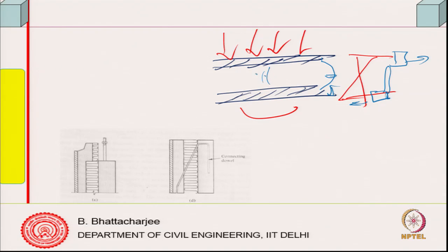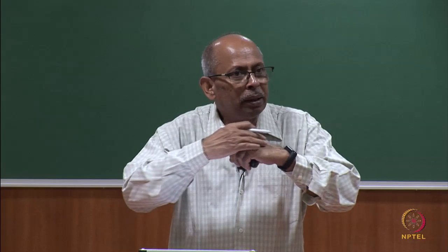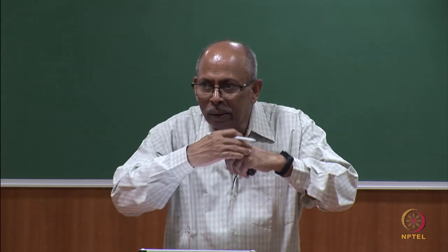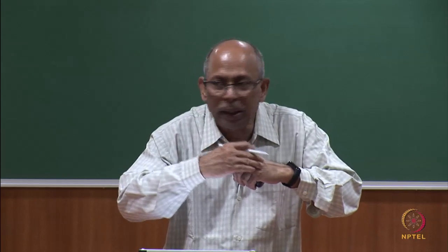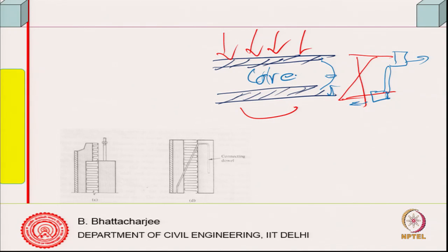So, this in between core, through developing shear stresses, allows transfer of load from top to the bottom, because it will resist the sliding of the top one and then so on so forth and bottom again. So, the core does not have to take the flexural tensile stresses nor the compression. So, I can model it in this manner, two rectangular stress blocks, and that is actually how it behaves. There will be, of course, some amount of stresses in this one also, but I am not worried.